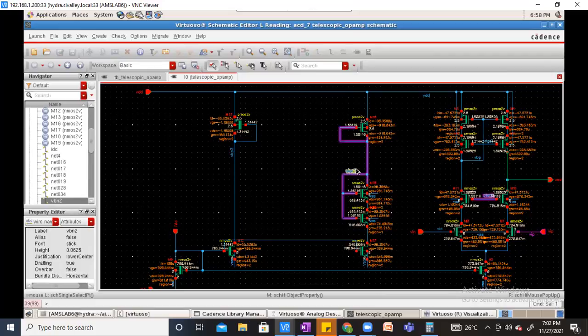Simple. And why is this directly connected here? Because I don't want to extend these branches further. I'm just turning it off, closing this branch. If at all you want to have one more branch here, then this need not be connected. You can just use it as a mirror and do it here, or you can use this as a mirror. It's like, after completing a sentence in your textbook or notebook, you give a full stop, right? This is kind of a full stop here. I don't want to extend my biasing circuit further. So how will you give a full stop? Just a direct connection.